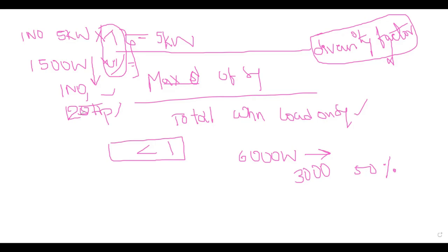As I discussed, I have 10 fans, but I won't run the 10 fans at a time. I will turn on one fan maybe from 6 a.m. to 7 a.m. Another fan will run at 10 a.m. to 12 p.m. Two fans. So there is some change in the maximum demand over a period of time.